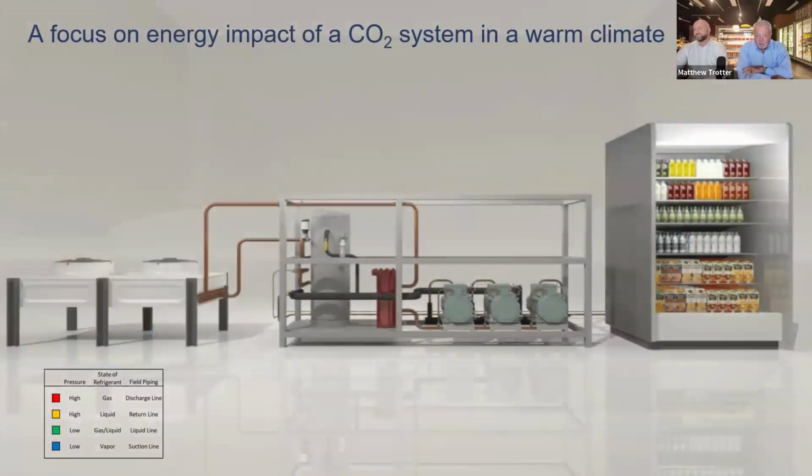There we go. Let's look at a refrigeration system in general, because we understand that a refrigerant, whether a natural one or the current synthetics that we use today, is used as a medium to remove heat. We want to remove heat from where we don't want it, in our display cases or walk-in coolers and freezers. We bring it back up through the system to the condenser gas cooler where we eject that heat